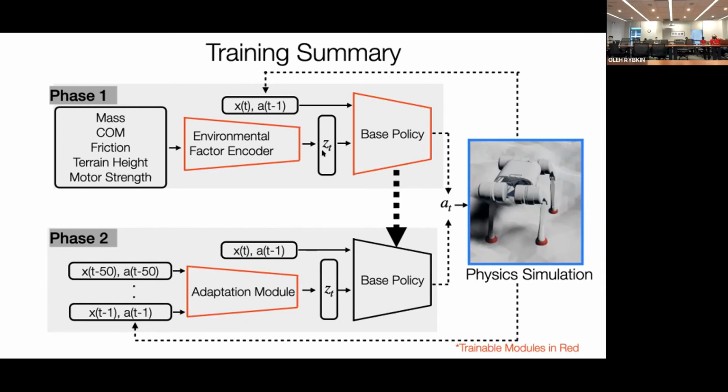And so, by predict the action, you mean you would train it with PPO, or whatever you were using for your RL, or you would train it with a supervised learning loss? No, I'll train it with RL. I'll keep everything the same. I'll just change the architecture to what you suggested. We did that, and the gaits were very unnatural because it has more ways to overfit to the simulation. So this compression and only looking at the current state helped it to have nice behaviors.